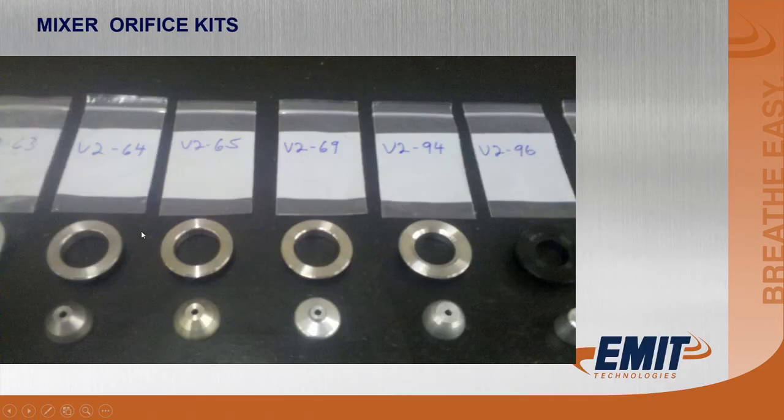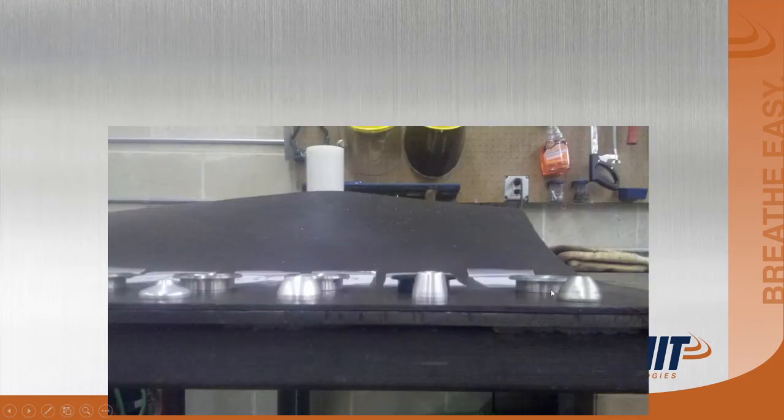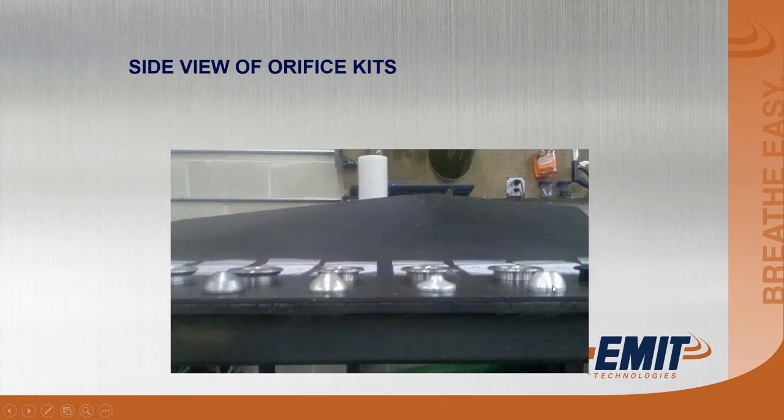A little look at the difference in the jets. You can see the difference in the bore sizes. These three are all the same bore size. This one has a smaller bore size, but if we get a cross-section view of that, you're going to see the difference in the gas valves. There's a big difference in gas valves. Always have to make sure you have the right valve for the right fuel and the right load. Makes a difference in how well they start and how well they pull the load. Again, more of them in a cross-sectional view.